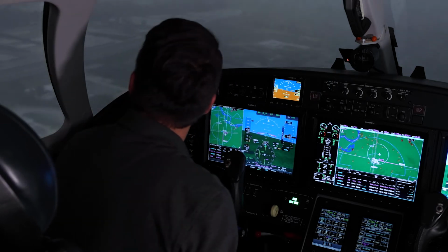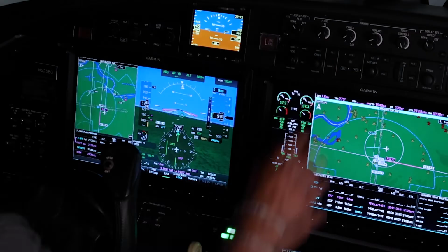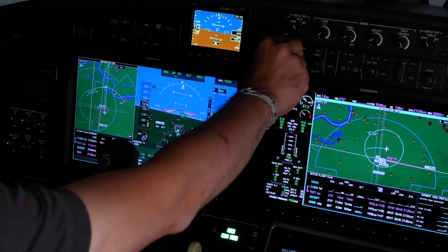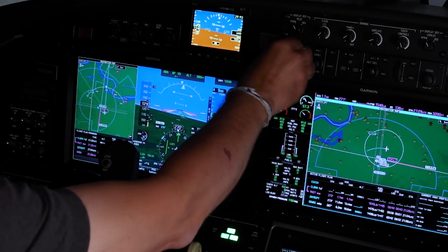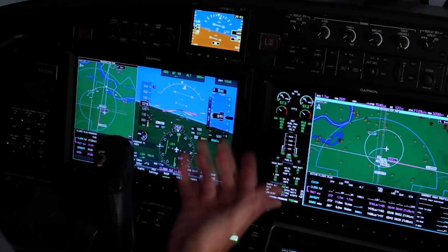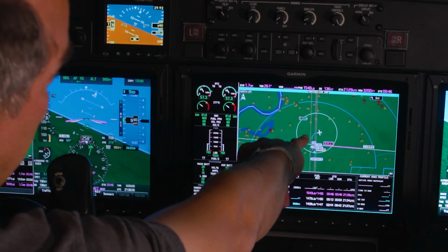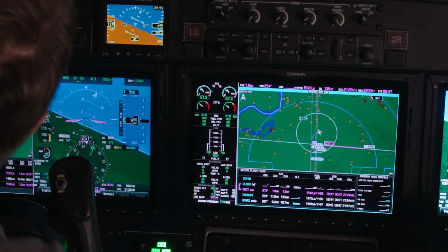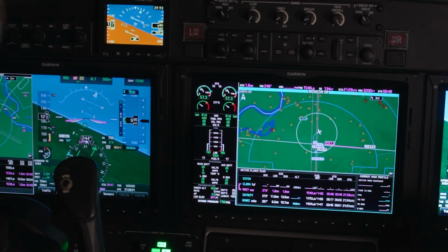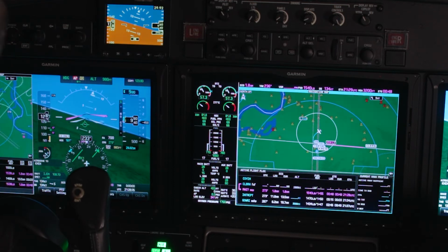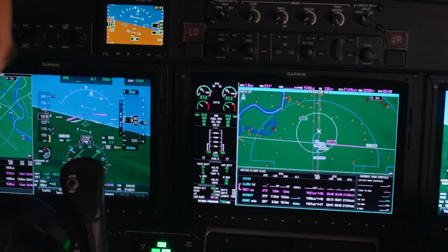Okay, I've got the left and center runways and the right runway, just maintaining them in sight. So again, knowing that if I'm going to err, I'm more likely to err by turning too late. I'm going to compensate by maybe starting to turn a little bit earlier than I think I need to. If I see on here that, okay, you know what, it is a little earlier, I can always roll out a little bit shy of the bank that's being indicated.